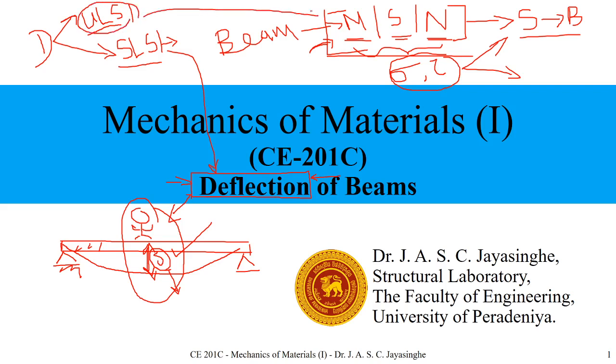Yes, it will come with these parameters. When you come to serviceability, of course there are some other parameters. The main one is deflection. You need to check, of course, when you come to static, deflection. And if you come to a dynamic system, you need to check things like acceleration and velocity variation also.